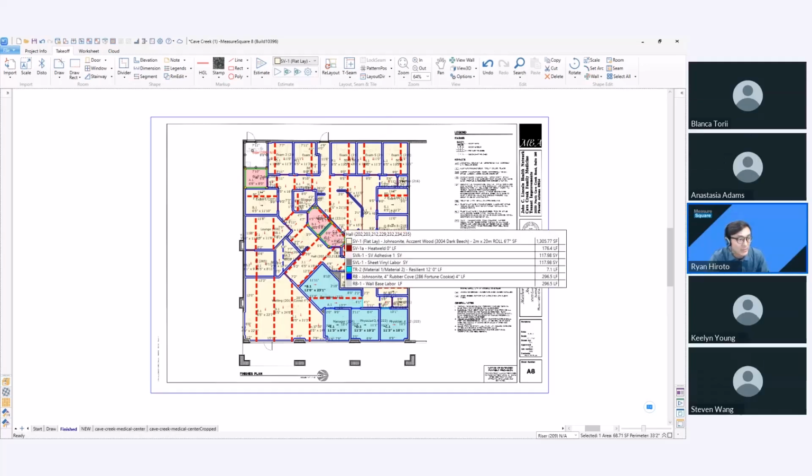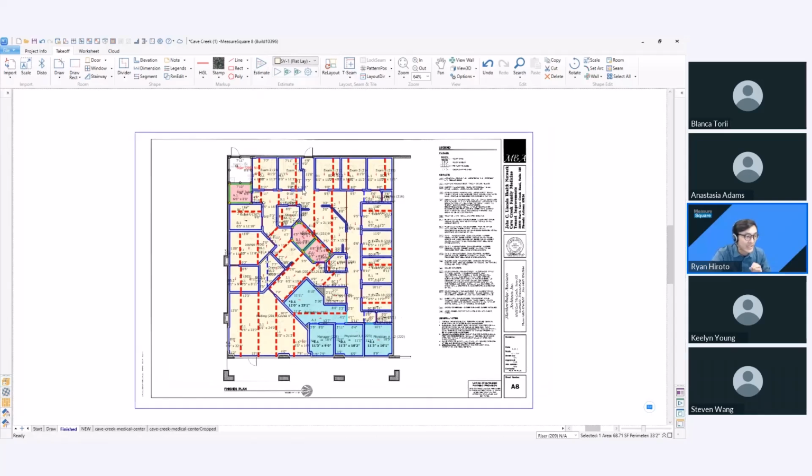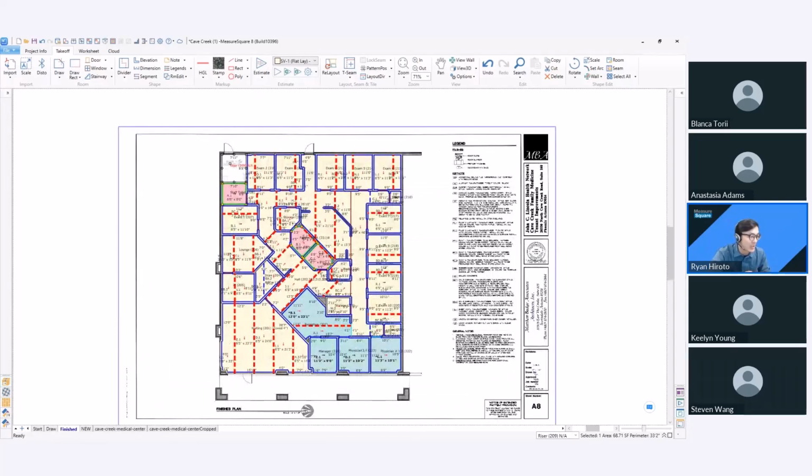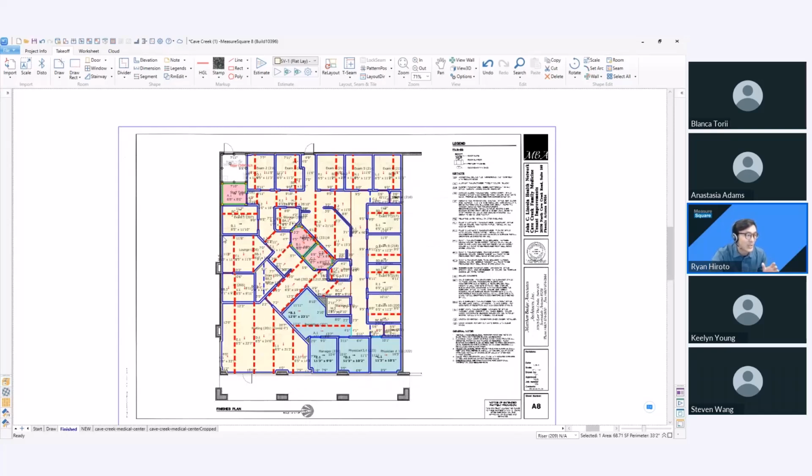So if you turn this off, you can go ahead and now adjust your large project to have the seam layout you want, and then just be sure you either turn this back on or you hit this estimate button up top to calculate for your updated cut sheet. Just a note there, because it is a huge time saver, especially when you don't need to calculate things right away. And we always want to make sure that our quantities are correct. So just be sure you do click on that estimate button when you're finished.